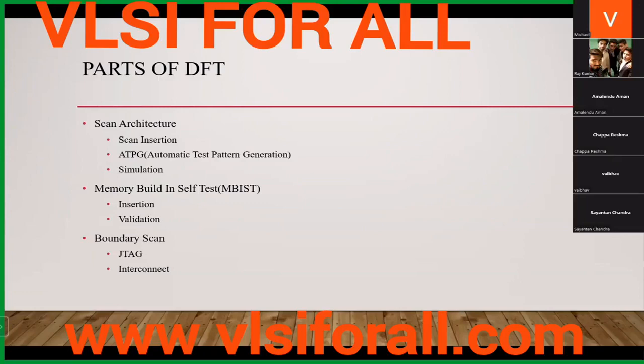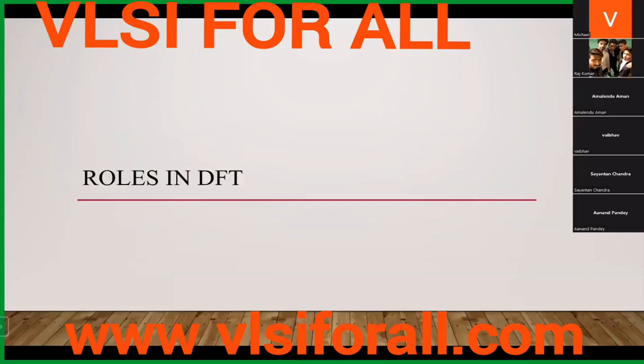multiple purposes, but in DFT we use it for interconnect testing, and we use it for programming our chip, and we have a boundary scan team who is doing the top level things during the testing. So there are interconnect tests also.